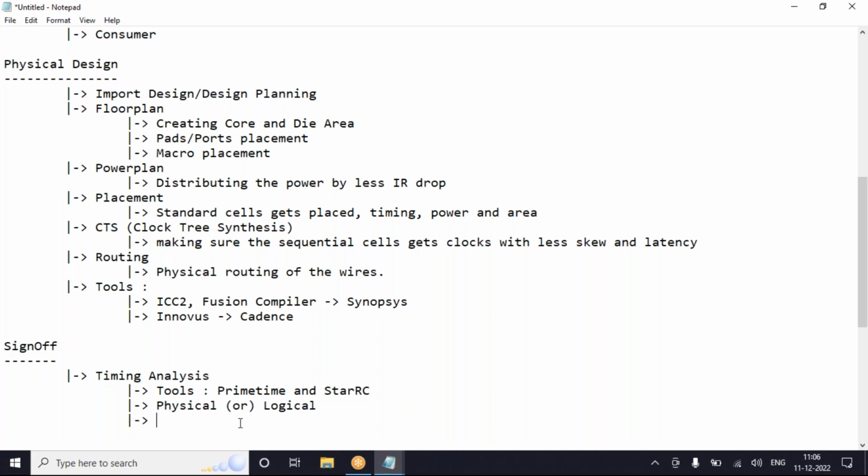So for timing ECO, you will invoke the PrimeTime tool based on the output of this particular routed database. You will perform the fixes in the PrimeTime tool and provide them back to the PNR tool, ICC. They will try to source it in the routing stage. They will fix it, and again they will try to provide us the feedback, whether it is good or bad, and we have to make sure that it is observed again.